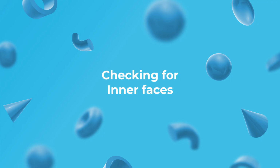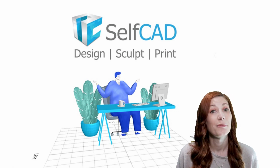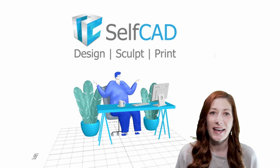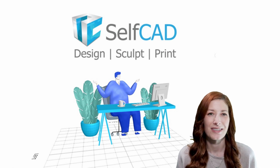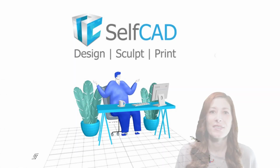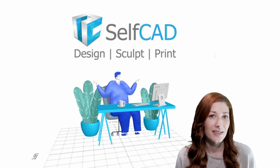Checking for inner faces. Inner faces are a problem because they disrupt the volume of the object, which should be completely empty from the inside. Interestingly, the Flip Normals and back face coloring tools can also help solve this problem. But there's one more tool that can help us solve this particular issue that we want to introduce: the back face culling. Back face culling uses the same logic as back face coloring, but it hides them instead of giving a different color to the inside faces.